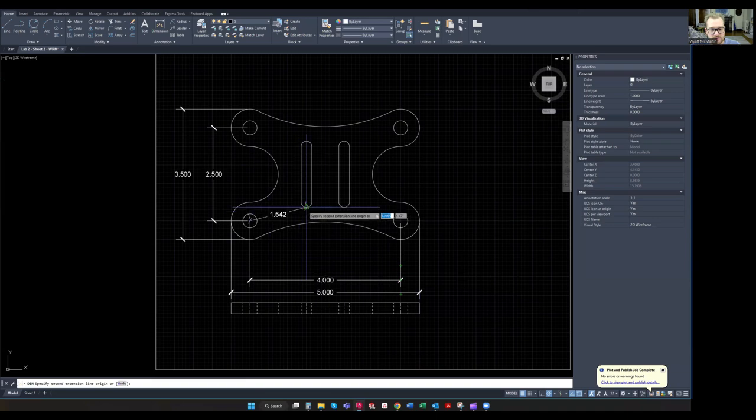From this circle to the second slot, and remember, it's going to give you a diagonal. So drag your cursor to the left of the leftmost leader, and then you can go ahead and place. Do it one more time. To this slot, same deal, left of the leader and place, just like that. Now we have them nicely organized here. Nothing's overlapping.